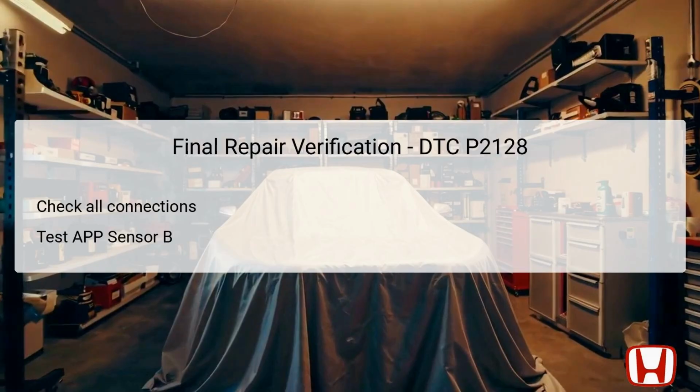Final repair verification is a crucial step after troubleshooting DTC P2128. Ensure that all connections, including the APP sensor and ECM, are tight and secure. Double-checking these connections will help eliminate any potential electrical issues related to poor contact.